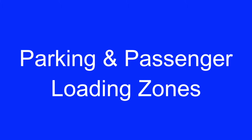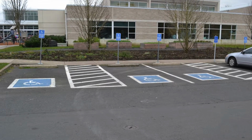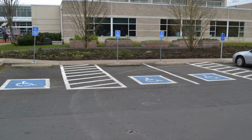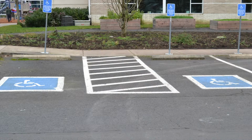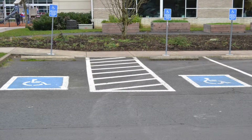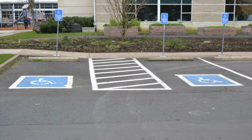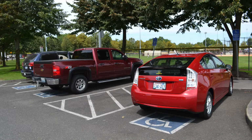Parking and passenger loading zones. Oregon law for accessible parking spaces is much more restrictive than federal standards. Parking lot design requirements set forth by the Oregon Transportation Commission require that the width of the parking space be 9 feet rather than 8 feet, and the access aisle be 6 feet rather than 5 feet for non-wheelchair users.